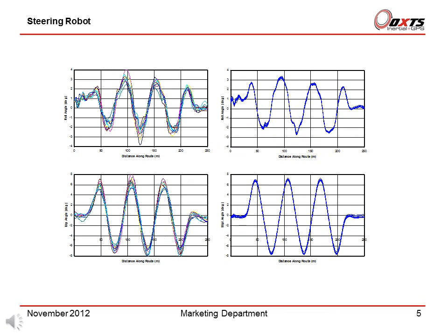As you can see here on the graph, the roll angle is at the top and the slip angle is at the bottom. These are also much more consistent using the steering robot. Car manufacturers are starting to pay a lot of attention to the way that the cars handle. Having the tools to measure differences is important. The robot is able to objectively detect very small changes in the vehicle setup.